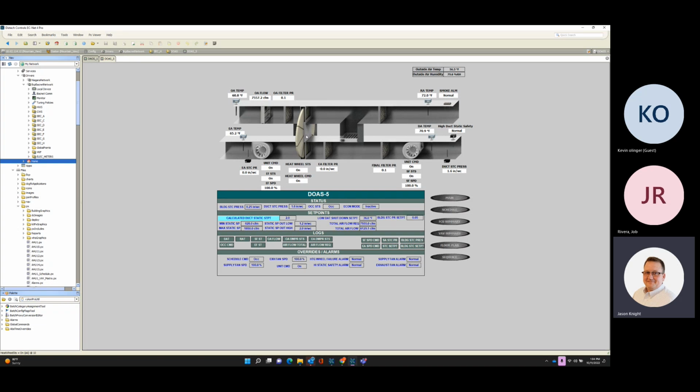So the challenge is going to be what happens this fall. With this campus, as soon as you start getting low ambient conditions into the 30s, we need to watch this thing really close and make sure these babies don't lock out. Or maybe initially set these at 28 degrees, until we can see how efficient this heating wheel is. How much heat are we actually recovering from this, and at what temperature can we maintain? We don't know what they're going to do yet.